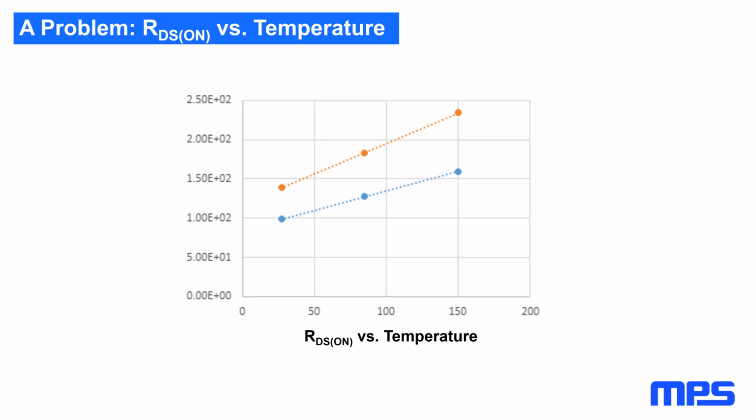That means the power dissipated in the FETs goes up, so the temperature goes up more, and the RDS on goes up even more, so you can see the problem. You can be very conservative and just calculate power dissipation using the expected RDS on at the temperature that would cause thermal shutdown, which is often around 150 degrees C. And if you're not careful with the PCB design, you might very well get to such extreme temperatures.